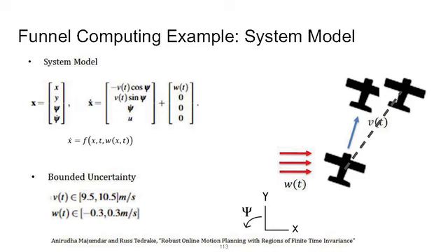So your velocity can be different from what you want. Say your nominal velocity is 10 meters per second, you can have some kind of drag, or you can have some inconsistency in your motors, and so what you expect is that there's plus or minus 0.5 meters per second to your nominal. So when you start writing your equations, this is what you expect your robot to do, and then that can vary forward and backwards depending on what your actual velocity is.